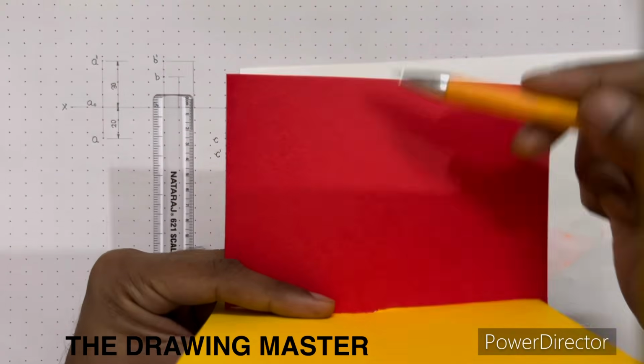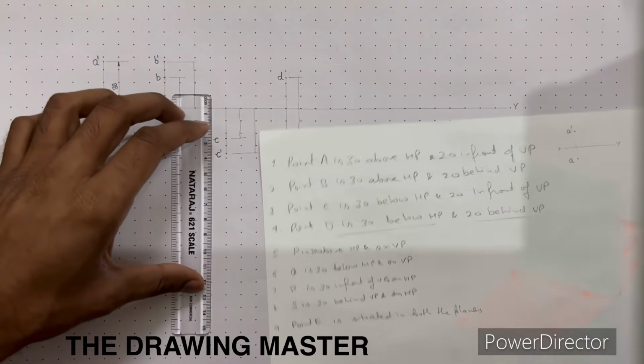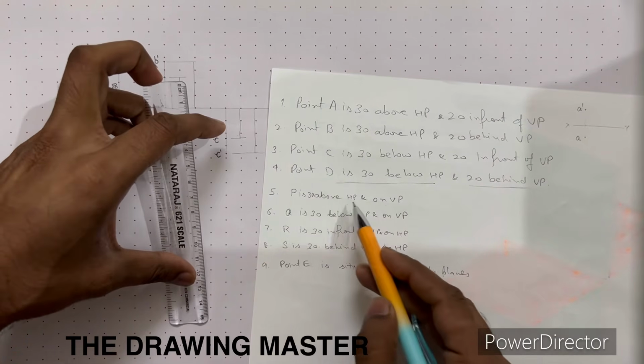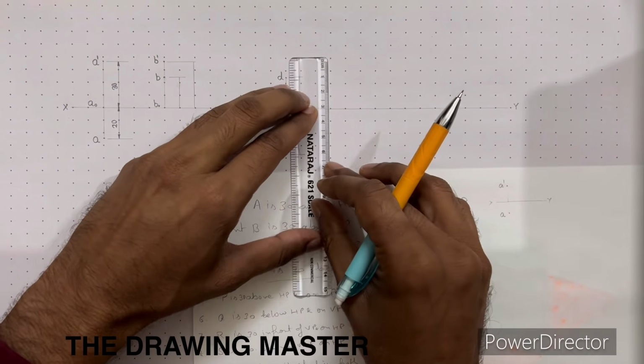So front view will be above the reference line. Point P is 30 above HP. Here one distance is 0, so no problem. P is 30 above HP, so above means above the reference line.